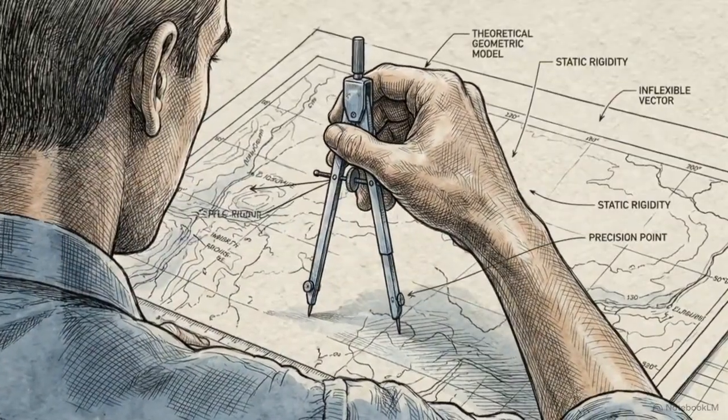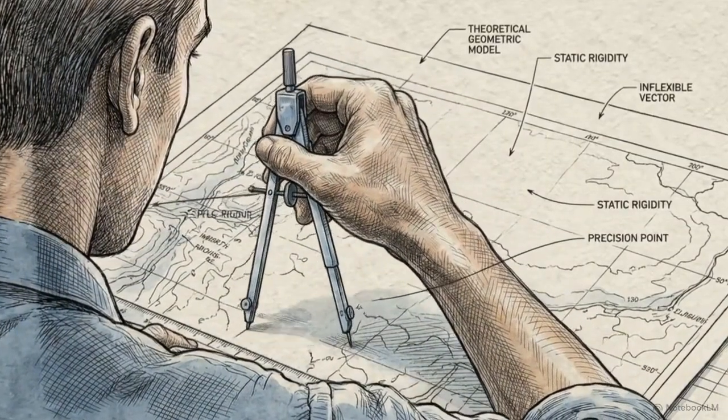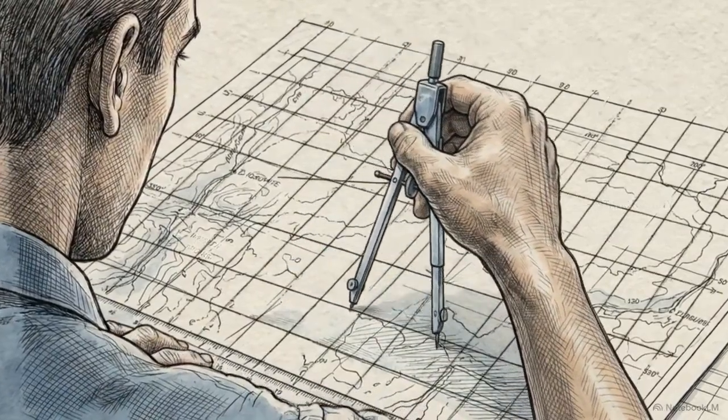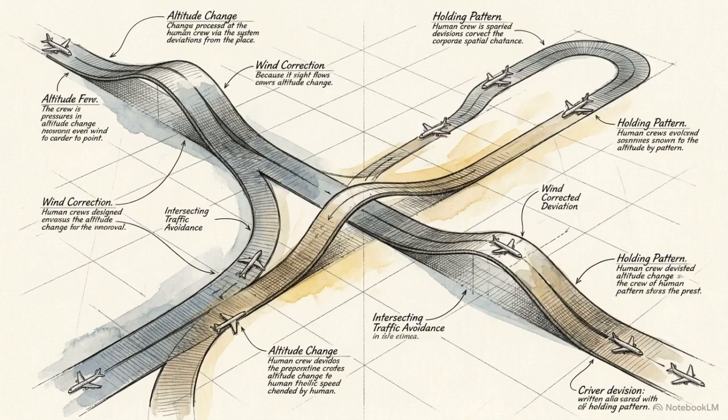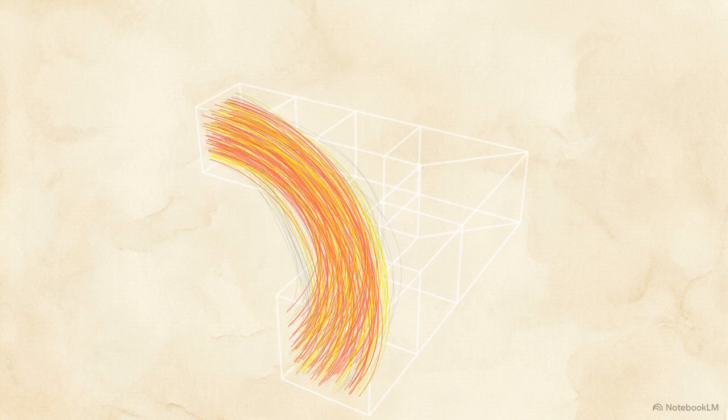Traditional airspace planning relies heavily on static, theoretical models. Planners draw routes assuming aircraft will fly perfectly rigid lines, which rarely accounts for the actual behaviors and shortcuts taken by human crews. This animated diagram illustrates that theoretical approach, a clean, straight 3D wireframe corridor representing a standard terminal arrival route. But when we overlay the historical ADS-B data lake onto this model, the reality becomes visible. Thousands of actual 4D trajectories, tracking latitude, longitude, altitude, and time, populate the space, forming a dense heat map of empirical execution. Planners can now observe the physical delta between the theory and the practice.